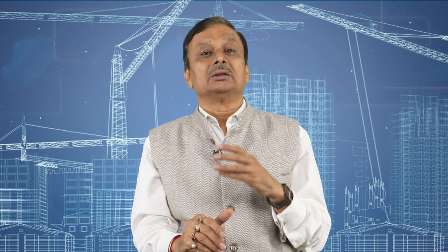Now, factors that affect the strength of concrete. We are concerned about how much strength the concrete is gaining. We have discussed in the previous lecture that concrete strength is affected by factors like the raw material being used for making the concrete, the water cement ratio, that is the ratio of water to cement, the coarse and fine aggregates ratio, as we just discussed, the age of the concrete, the compaction of concrete, the temperature and relative humidity, and curing of concrete.